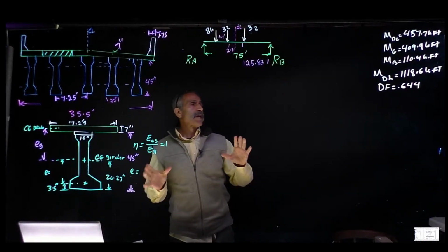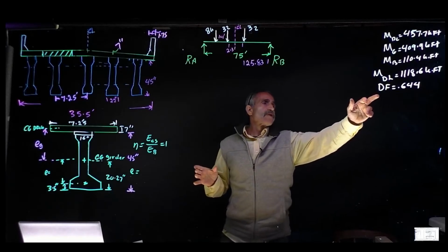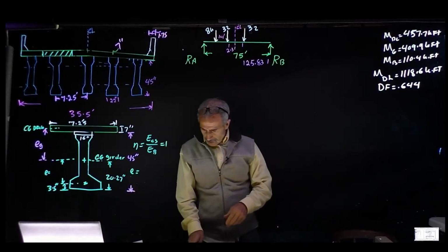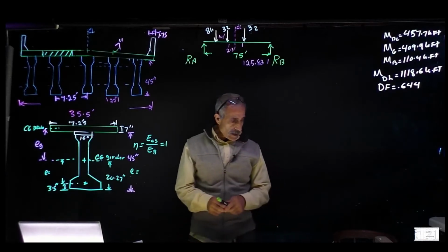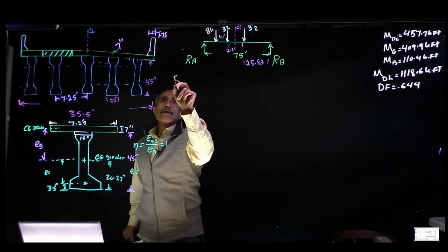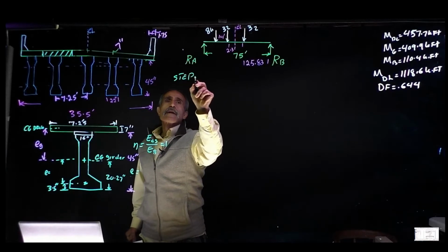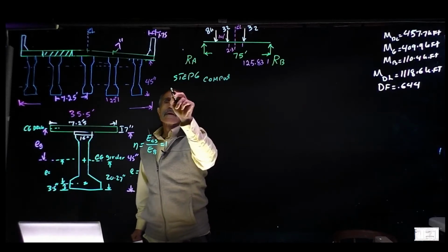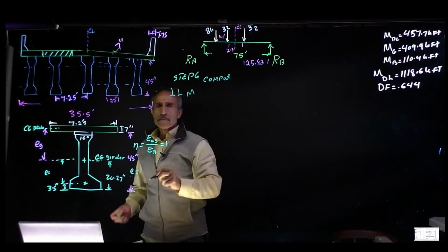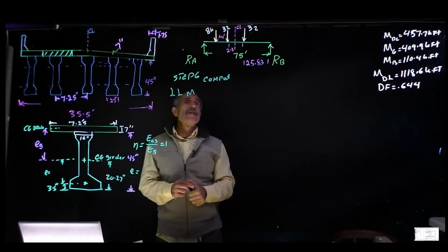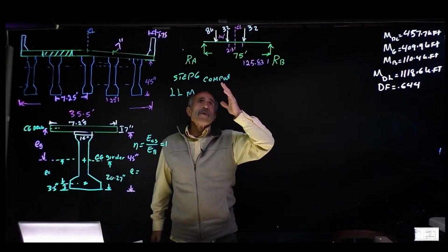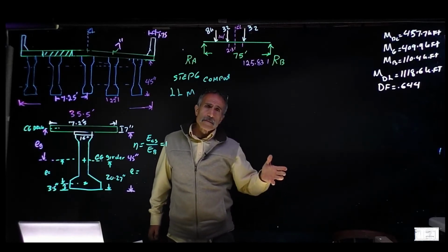Okay, now we've calculated the live load distribution factor. Step number 6 would be to calculate live load, compute the live load moment. We talked about this before, and there's a video on it. We even did it in Robot.